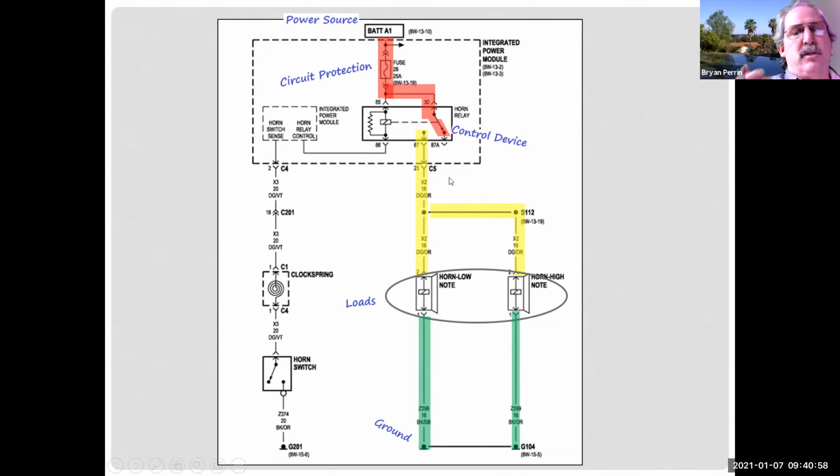And I did buy some of those. It's a little relay tester. What it does is you take the relay out, you plug it in, and then you plug the relay into the top of it. And then it has the little tabs that are numbered along the side of the tester, so I can do all my tests there with the relay in place. So I can actually watch the relay work. I can apply power and ground.